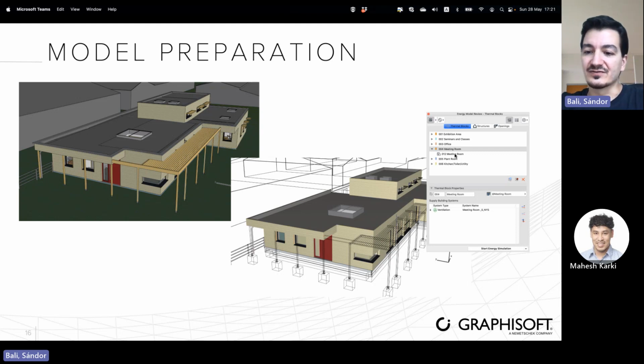Basically, those zones which have the same function, the same indoor requirements, the same orientation, and the same building systems. Even if we don't know exactly in the beginning what those building systems will be, but we know that they should have heating and cooling, for example, the same type of heating and cooling, then they will belong to the same thermal block. So this can be a simplified grouping, or it can be a more detailed grouping depending on the level of detail in our design.